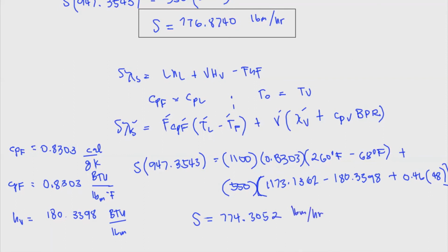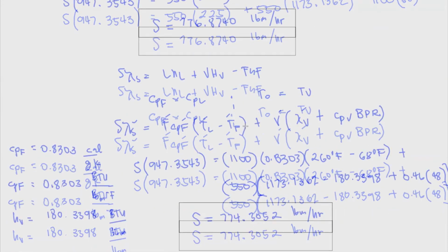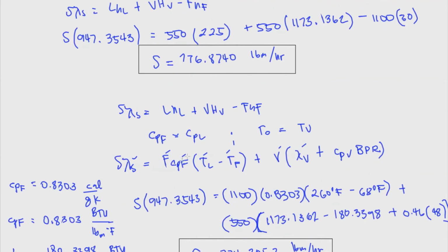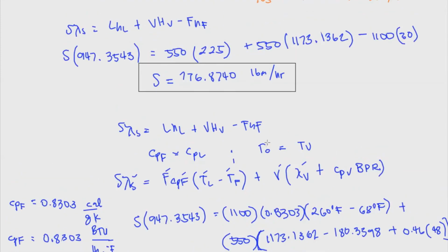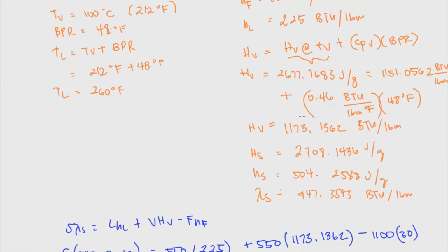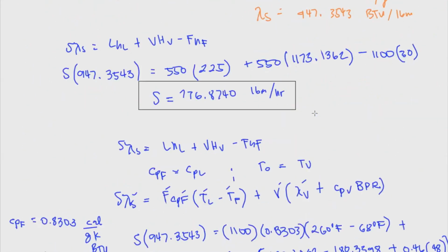Okay, so as you can see here, we really have a close value using either way. We have the enthalpy and this heat balance. This is easier done when you have all the necessary values, but of course when you have different enthalpy concentrations available to you, this one is a lot easier.